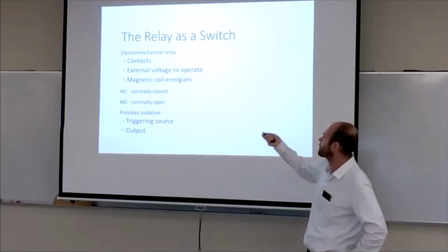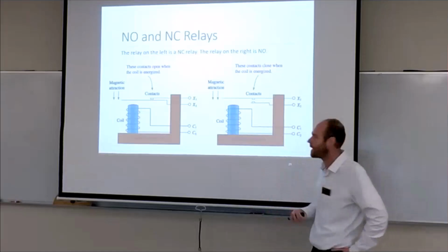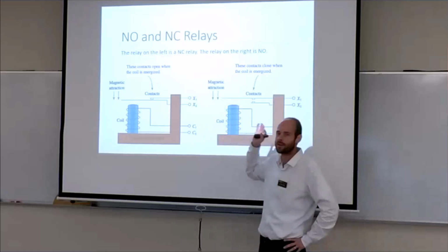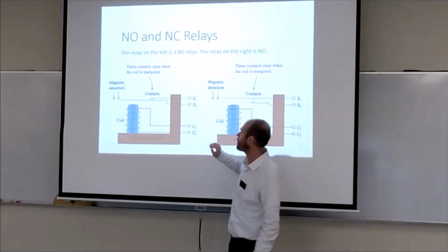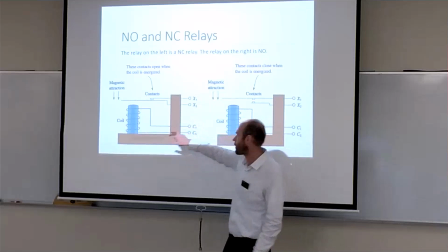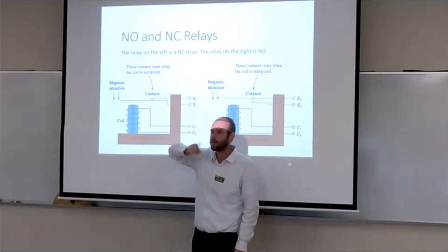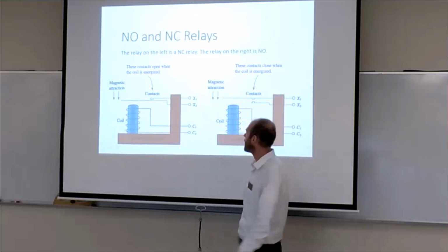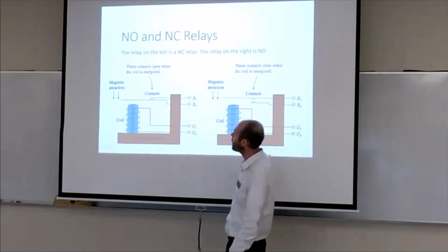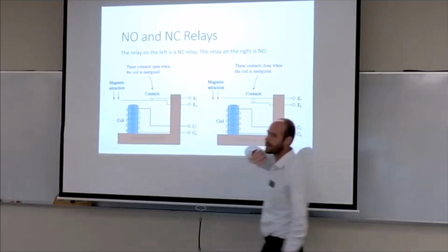We're almost there. We just want to mention relays a bit. Electromechanical relays work with coils and contacts. These will be used if you do want a mechanical connection to be made or broken or isolated from your digital electronics. We can have some electronics here being driven by a coil. This coil will run current. And what happens when we run current through a coil? Magnets. Yeah, we create magnetism. And so depending on the setup of your mechanical switch, it can be normally closed or normally open. You create magnetism, pull down that lever, and you can open a contact or close a contact.